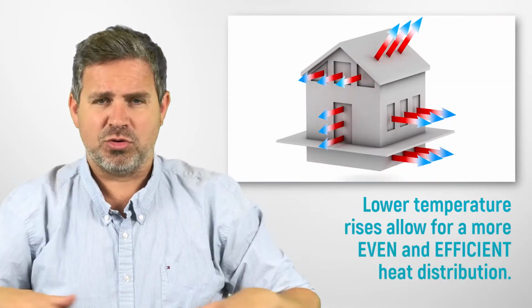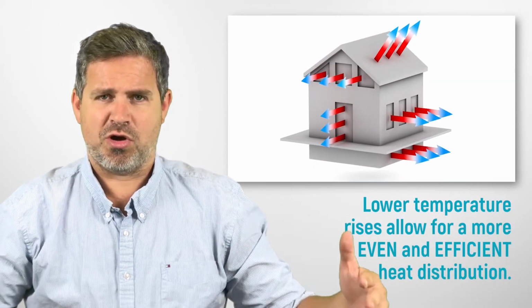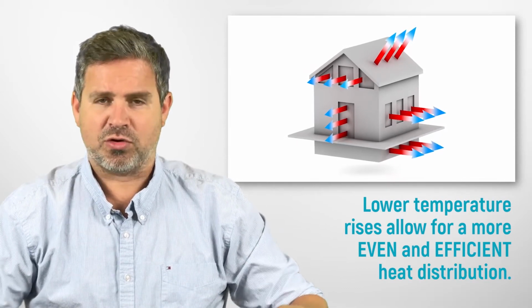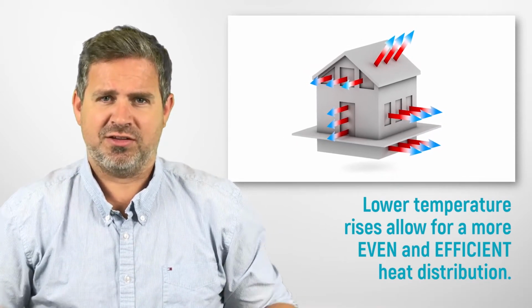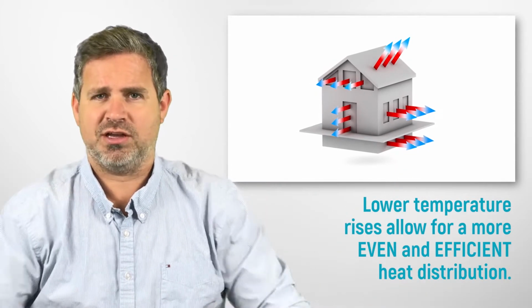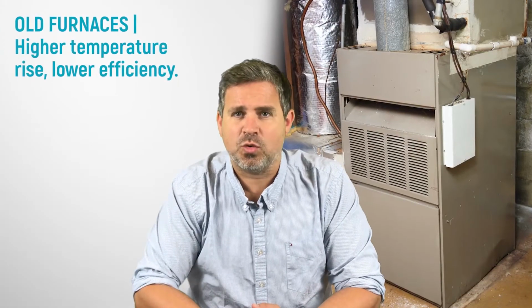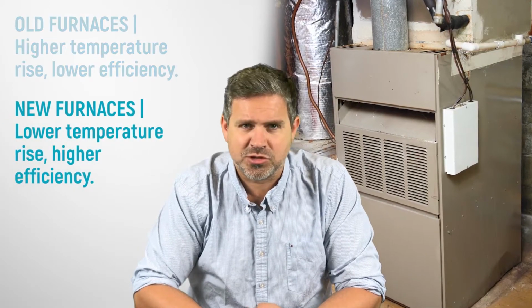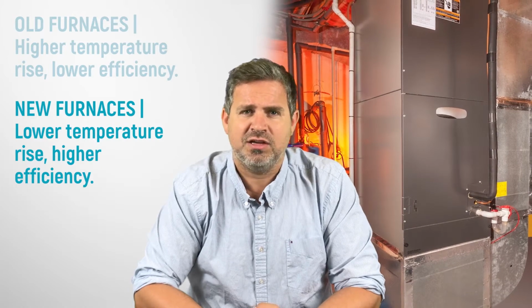By more slowly heating the house, newer, more modern furnaces have a lower temperature rise. It more slowly brings everything up to temperature. There's less of a chance for the heat to dissipate and disappear. It spreads more evenly throughout the house. So older forced air heating systems have a higher temperature rise, and newer forced air heating systems have a lower temperature rise. So what are the alternatives that you have to forced air heating?